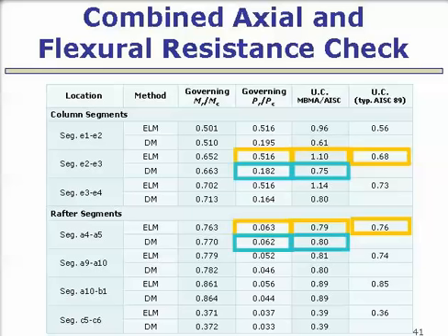We're paying a little bit of penalty there because we've actually got imperfections in the frame, and we need to deal with the uncertainty in stiffness. When we deal with that in the direct analysis method, we get slightly higher moments. So that tends to penalize us a little bit in many cases in the rafters. A 0.01 penalty here. If we look at the typical unity check from prior type calculations, 0.76.